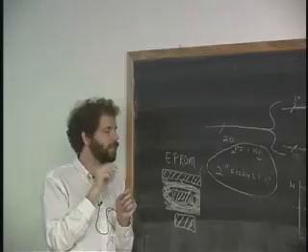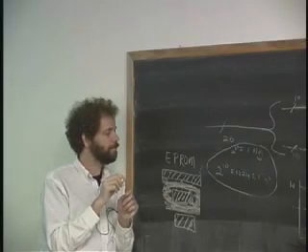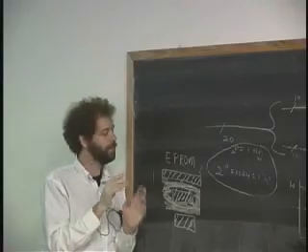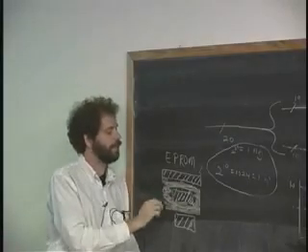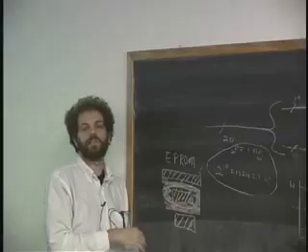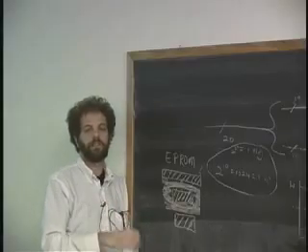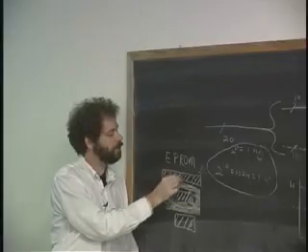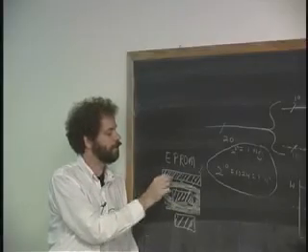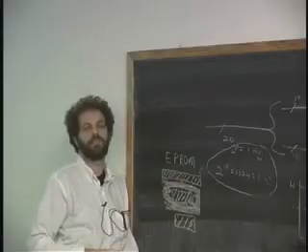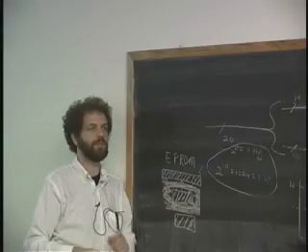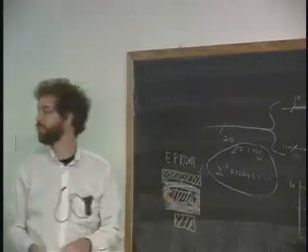If you shine a really strong ultraviolet light of a certain wavelength, and certain wavelengths work better than others, depending on how the glass is made, it'll allow all the charge to leak off, and you'll basically clear the ROM. And then you can program it by setting certain of these plates to a high voltage, and it'll allow the charge to sneak on to certain ones. And that's how it's done. Okay, so if you ever see these chips being made, you'll actually know how the thing works. And you'll think about bathtubs, right?